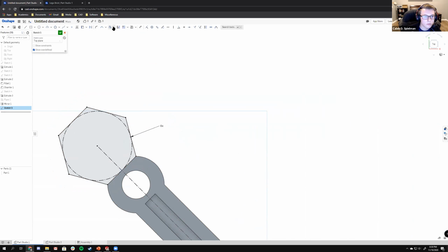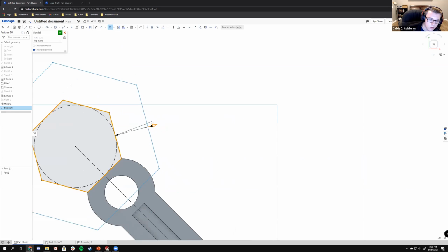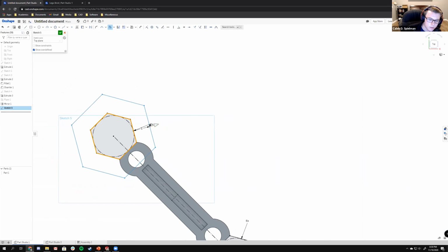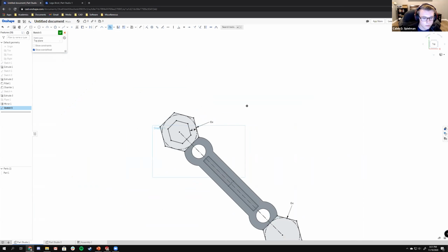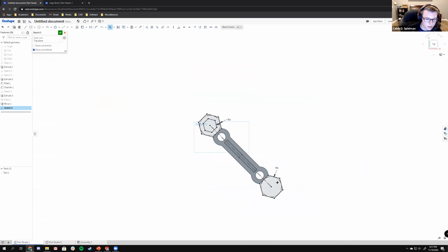Okay. Offset tool. Clicking the lines. And then there's this arrow. It pops up unpredictably in unpredictable places. This right here, this little arrow defines the direction in which the offset is being conducted in. So I'm just going to click that. And now I can flip the direction. Ooh, flip the direction. Okay, enter, and I'll define this as 2.5 millimeters. Okay, that's the offset tool.